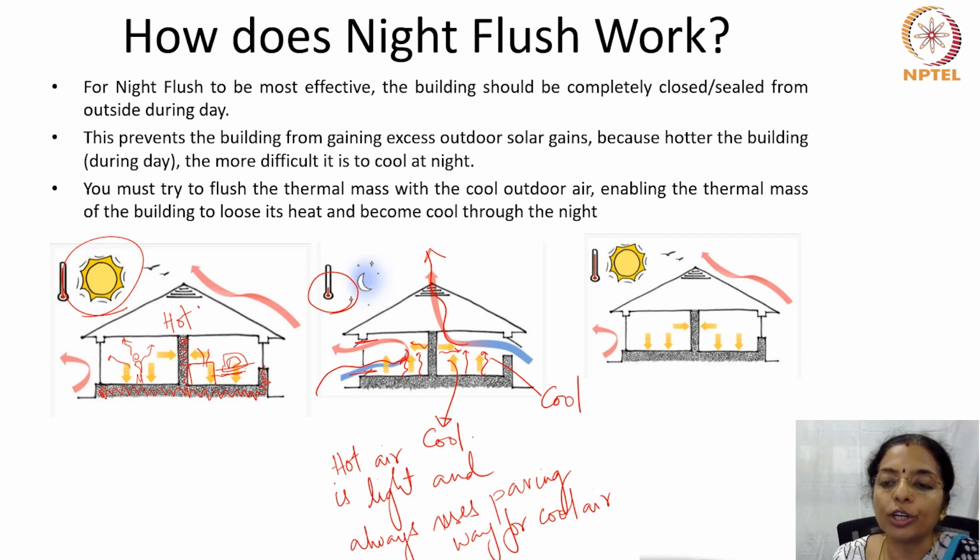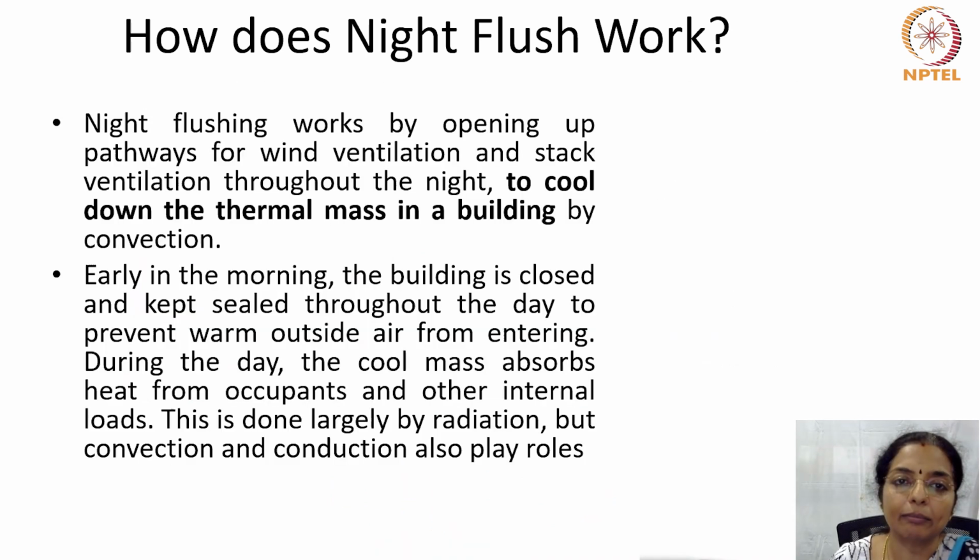At that time, what should you do? You should close all the openings. So the inside remains cool during the day, and in the evening again, as the people and the contraptions would have radiated the heat and the indoors become warm during evening, again open the window at night and continue this cycle.